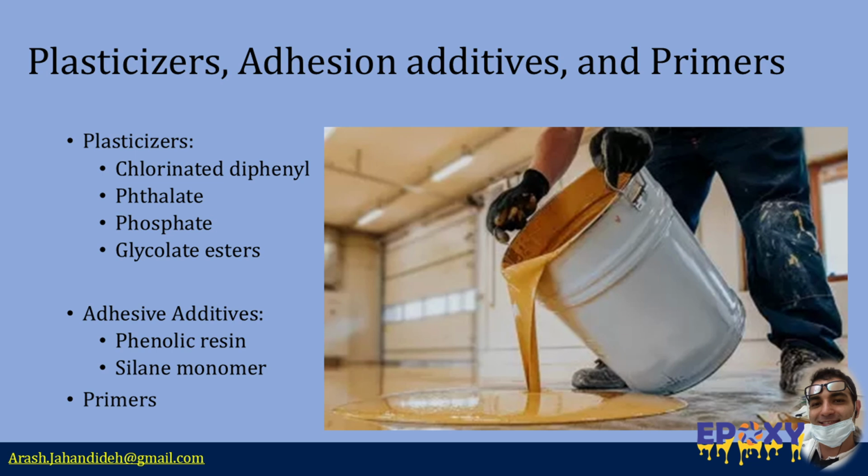In one-part sealants, a silane monomer is used to provide chemical bonding to inorganic substrates. For aircraft sealants, where chemical resistance is essential, a more fuel-resistant phenolic resin such as Durez 10694 from Occidental Chemical Corporation is preferred.